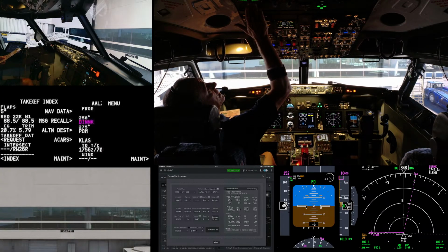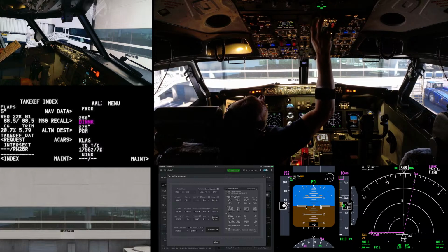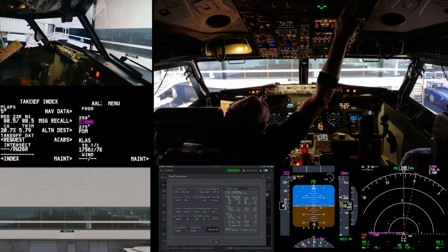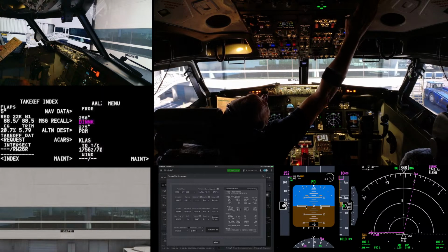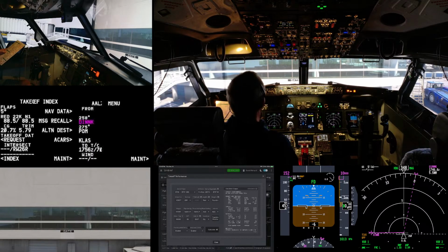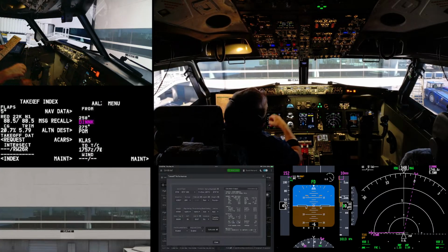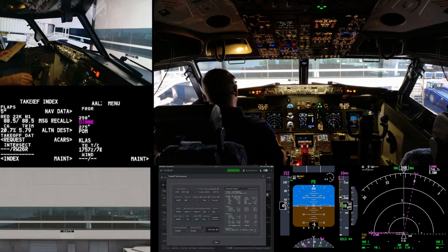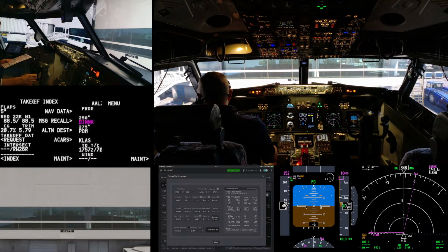Pre-flight leading edge devices checked, service interphone is good, engine reversers are extinguished, EECs are on and guarded, flight recorder check, crew oxygen 16, passenger oxygen is set, is normal and guarded, Mach speed 1, Mach speed 2 check, stall warning check, good, stall warning number 2 check, confirmed.